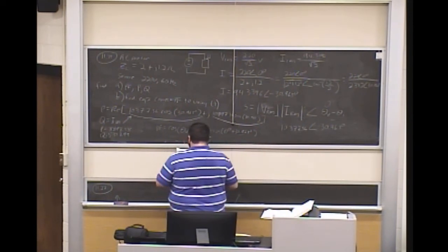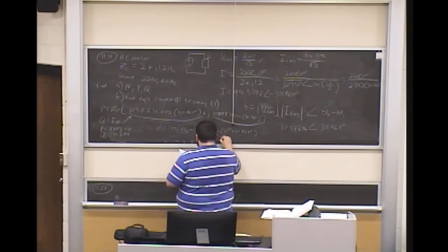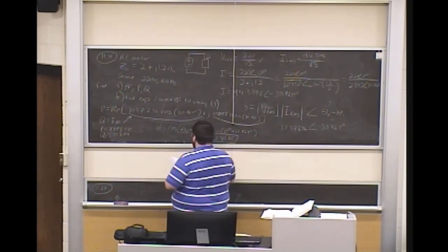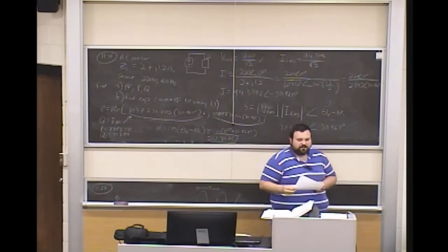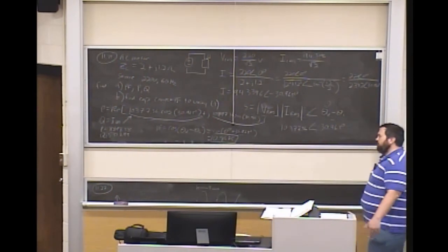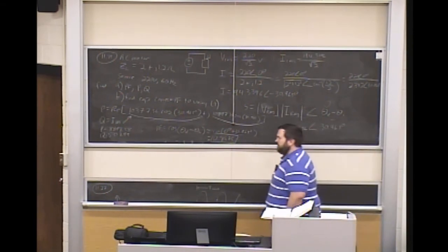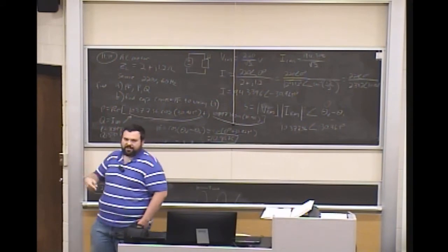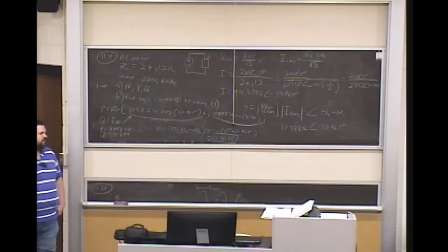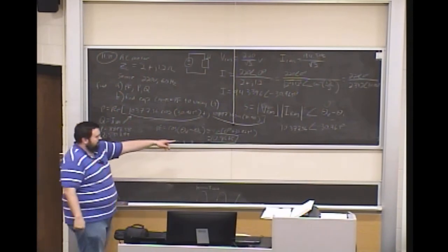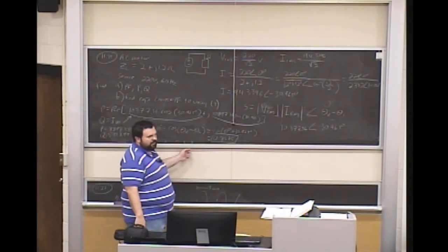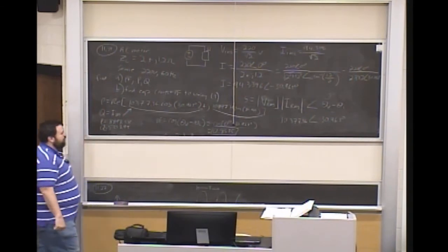And so that works out to just be 0.8575. So that's your power factor. Now, in an ideal world, we want our power factor to be unity, meaning 1. Okay? Unity is a good word to know, especially if you're going to be a double E. When people say unity gain, they mean gain of 1. So get in the habit of understanding the word unity. In this case, not ideal. Okay? So we've got 0.85.